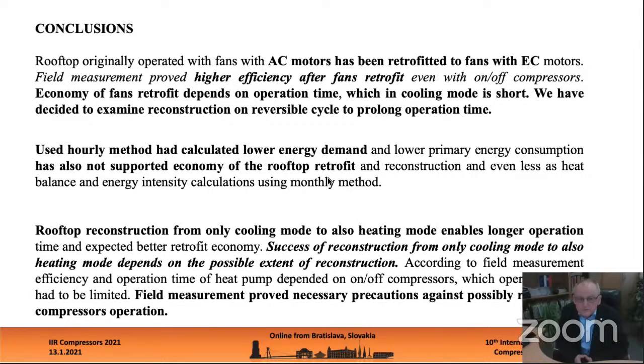Rooftop reconstruction from only cooling mode to also heating mode enables longer operation time and expected better retrofit economy. Success of the reconstruction depends on the possible extent of reconstruction. Field measurement proved necessary precautions against possibly risky on-off compressors operation.